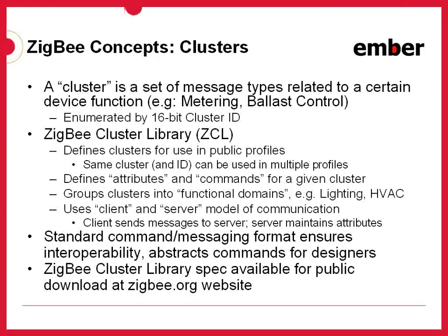The ZCL also stresses a standardized messaging format for commands, which ensures a level of interoperability, and that means a designer doesn't have to come up with their own ways to say, turn this light to 50% brightness, because there's already a level control cluster that says, please adjust the level, and then there's a standard parameter in that command that defines the level.